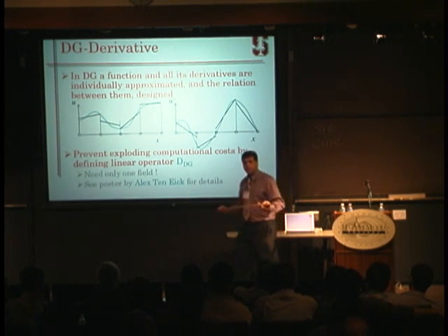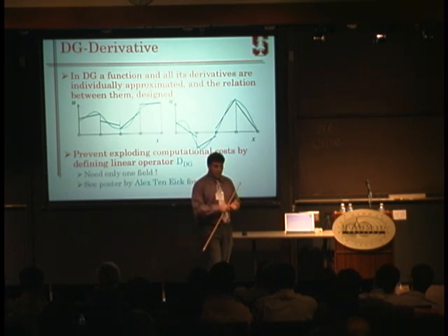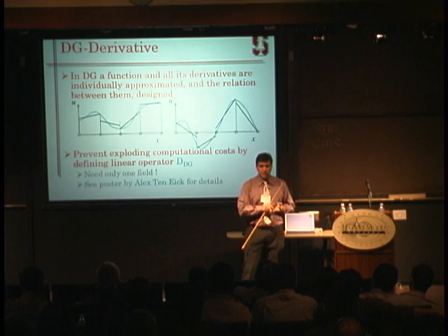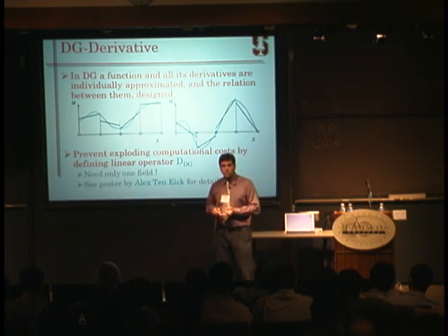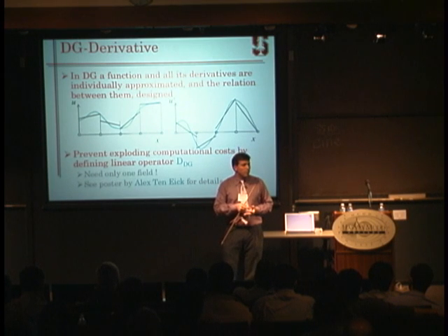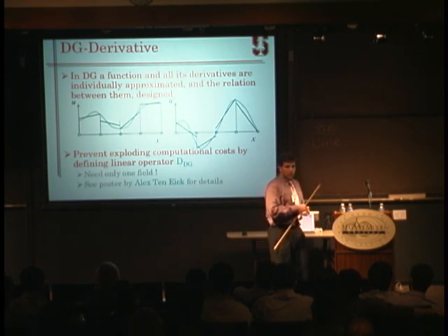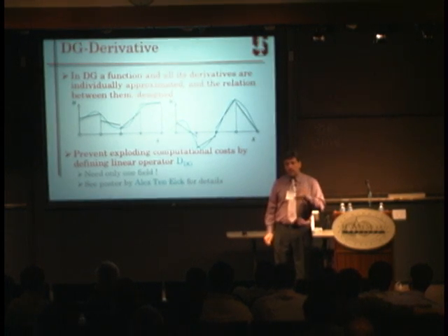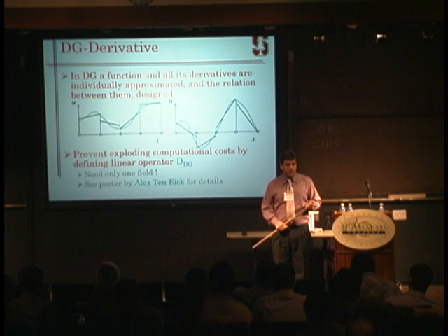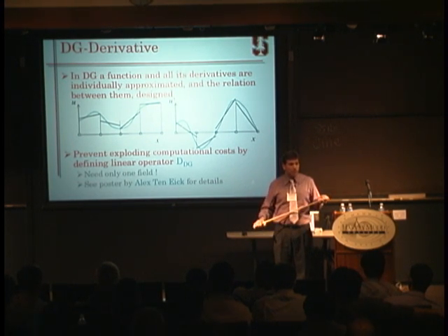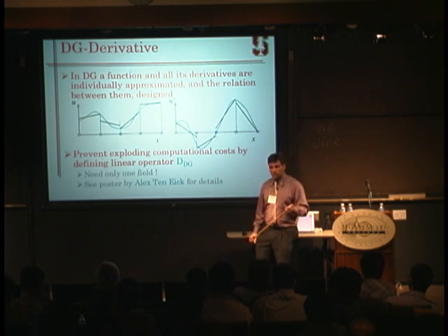The problem that we have here is that if you initially had 3 degrees of freedom per node to describe the motion of each node in space, now if you have to keep also track of all the components of a 3×3 second order tensor, you have now 12 degrees of freedom per node. So suddenly the size of your problem has exploded. That's a really tough benchmark to beat, okay?